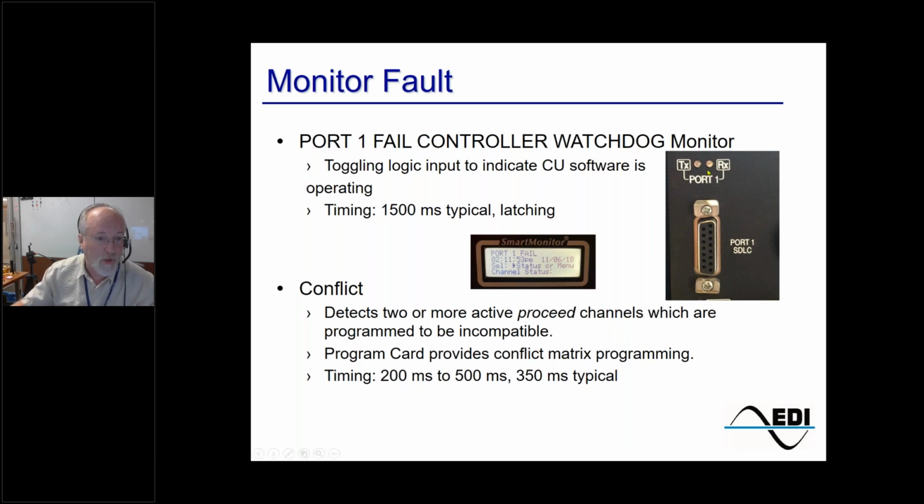If you check on the monitor, that one's working. You check on your controller, that one's flashing. Then you want to start looking at your BIUs, and you have your 3 BIUs. You would have one in your detect rack, and then you usually have 1 or 2 in your load rack where you'd see your load switches. So that's the BIU, and you want to make sure they're all flashing. If they're not, you're going to get this port fail.